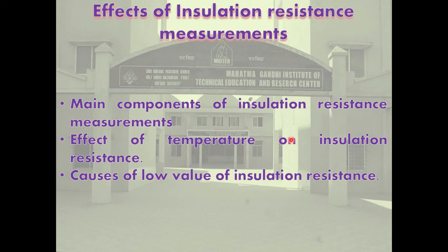The remaining two components, ILC plus ILS, are constant for a given applied voltage and are the true indicators of the insulation resistance. Wet insulation increases conduction currents through the insulation. Dirty surface of insulation increases the surface leakage currents. Since the capacitance current and absorption current reduce to zero after about 60 seconds to 10 minutes, IR 60 second and IR 10 minute give better indication about the quality of insulation.